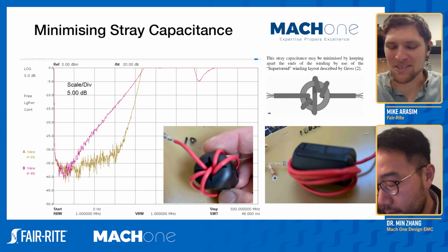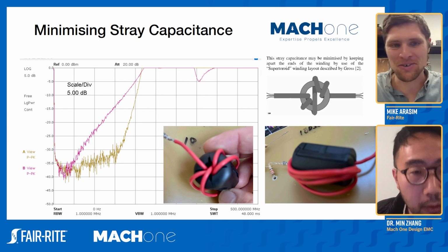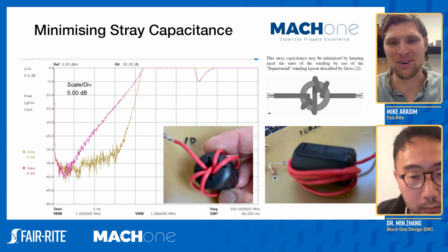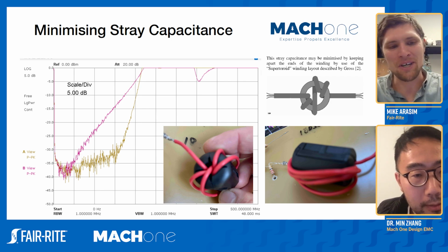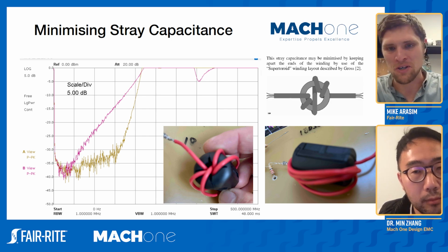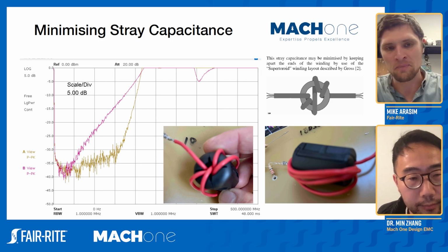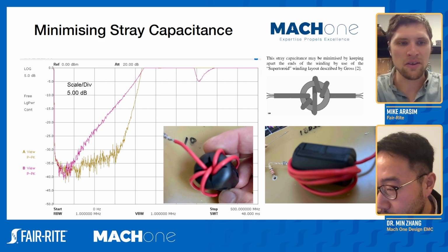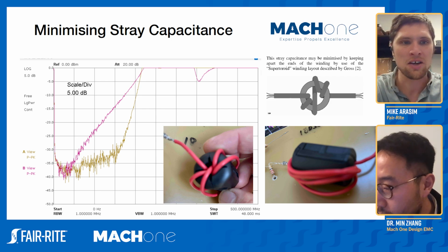It can be. The very obvious thing to consider, without being too funny, is whether the inner diameter of your core can actually fit multiple turns. But at the lower turn counts, and especially at the lower frequencies, typically more turns is going to be better. You'll get a higher impedance value, but that does come with some drawbacks as you start increasing that turn count.